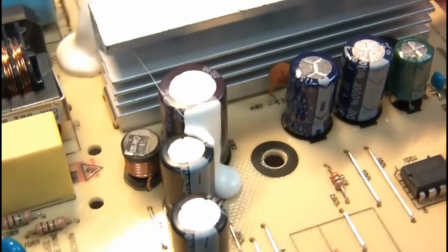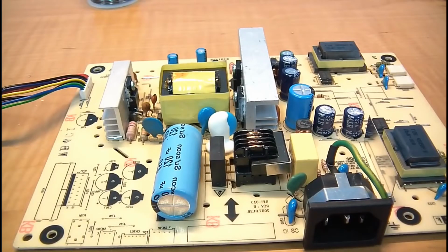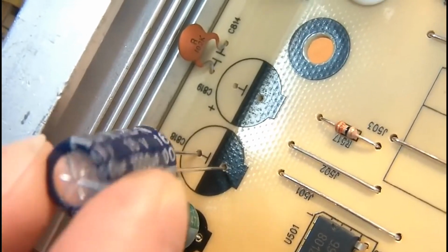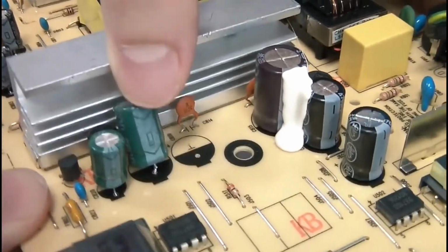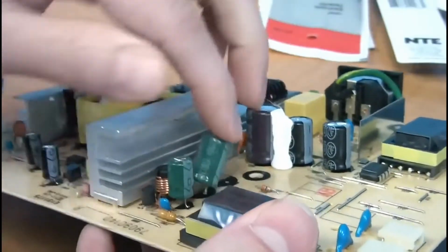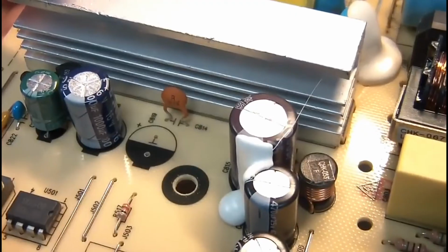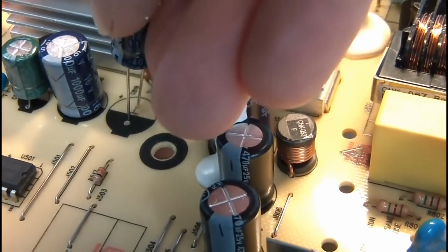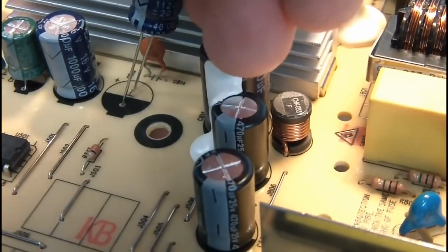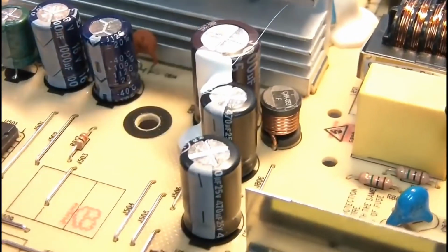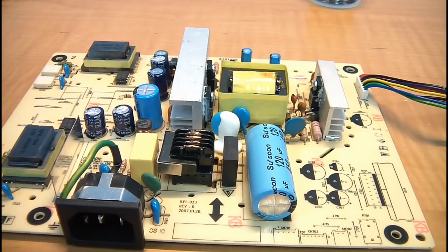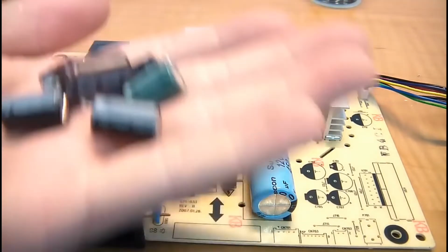Dielectrics in capacitors serve three purposes. First, to keep the conducting plates from coming in contact, allowing for smaller plate separations and therefore higher capacitance. Second, to increase the effective capacitance by reducing the electric field strength, which means you get the same charge at a lower voltage. And lastly, to reduce the possibility of shorting out by sparking, more formally known as dielectric breakdown, during operation at high voltage.